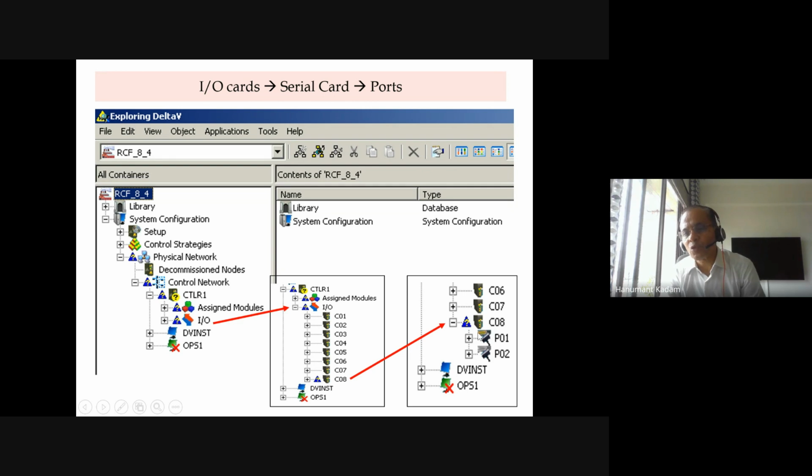So you can see you have something connected on port 1 here, and this is showing error. So you can see, it is easy to identify where your problem exists. Even though this triangle is here, which is on the physical network, which is on the controller, which is on IOs, which is here also, then you identify this card has some configuration mismatch.